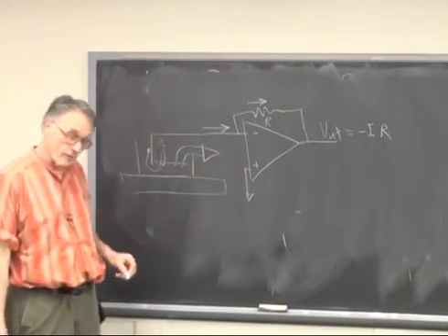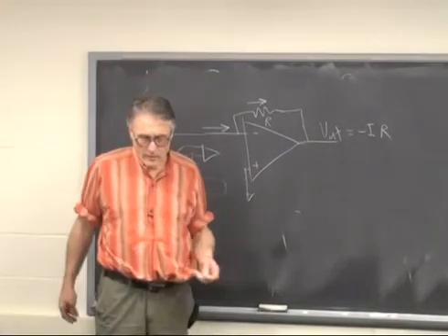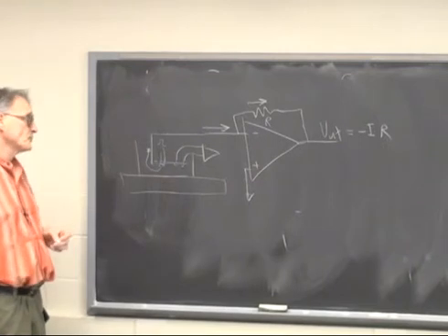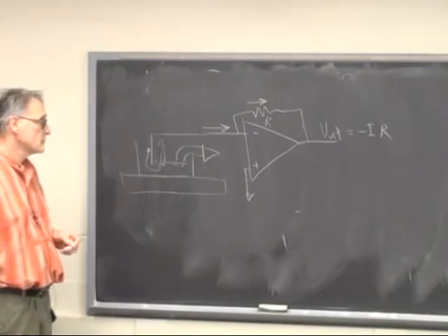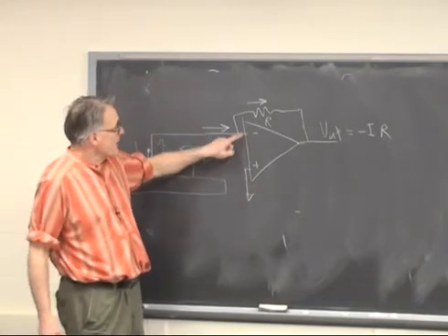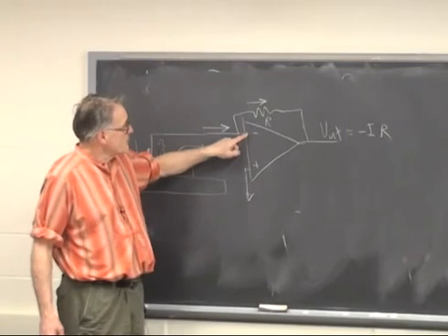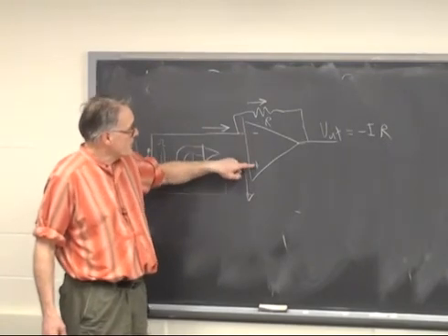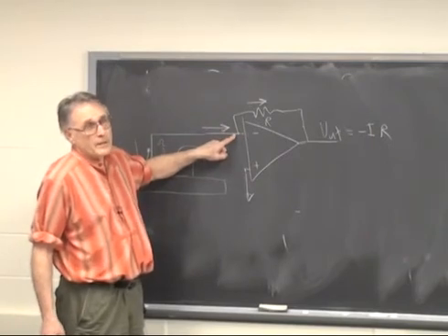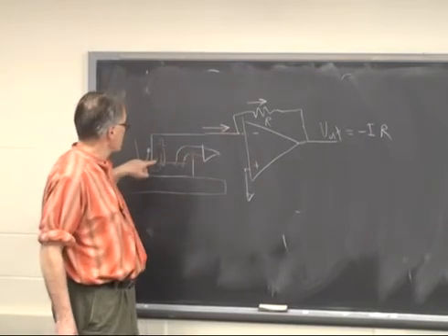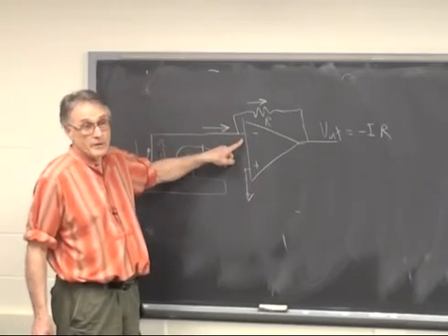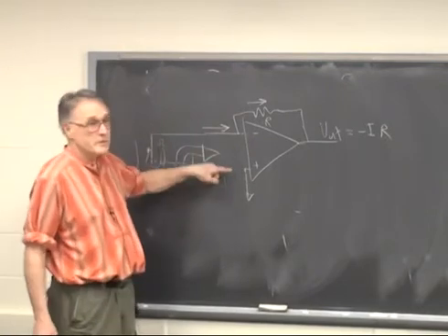So you can sometimes measure stimulus currents by using a virtual ground. You can also look for ground faults. You can look for anomalous current flows due to noise sources. Because this is an active system, and this point is being driven to a ground by the op-amp, the impedance of this point can actually be lower than just connecting the ground to a steel plate. This can be a better ground, a better quality ground, than merely connecting this wire to a steel plate.